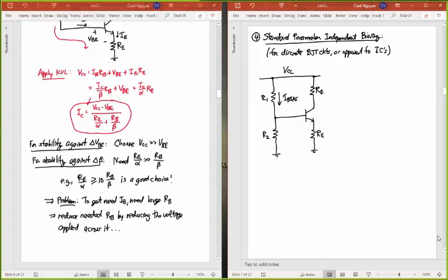And so how do we analyze this circuit? Well, a good way to look at this circuit is to just equate it by making the Thevenin equivalent of the R1, R2 voltage divider. Right? So this hopefully you can recognize as just a voltage divider.